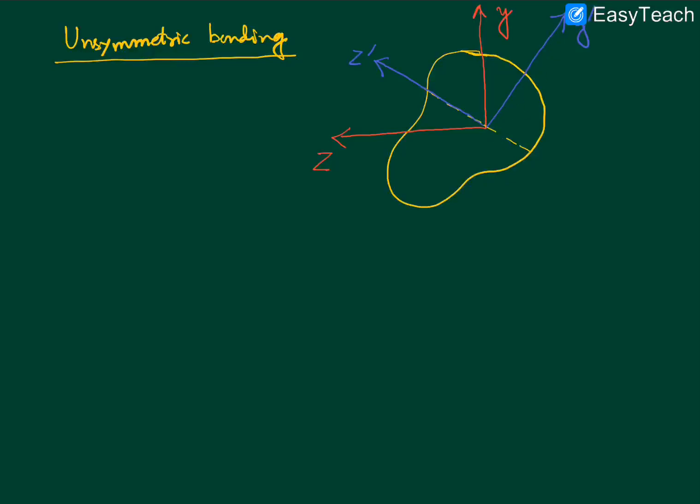So my hope is that the bending stress that will emerge on this cross section, the sigma xx, which will be pointing either out of this plane or into this plane, will have some sort of linear distribution, and this is very, very important, so I repeat it.